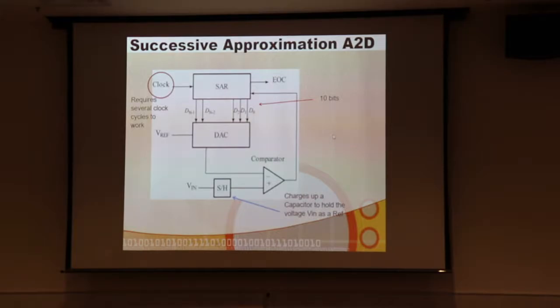But still, it works pretty well. And for signals that are not changing very rapidly, it can be very accurate. And you can average it yourself. Just read in 10 values and then do the average, divide by 10, or better yet, read in a power of 2 and shift it.